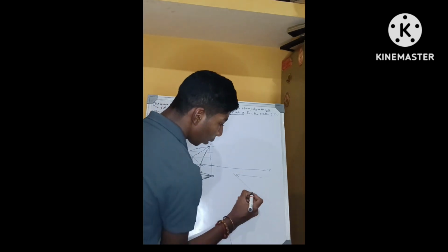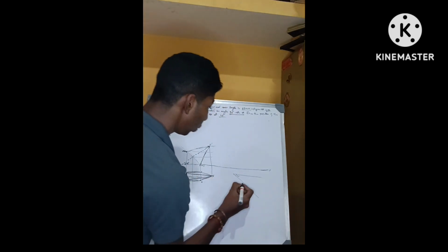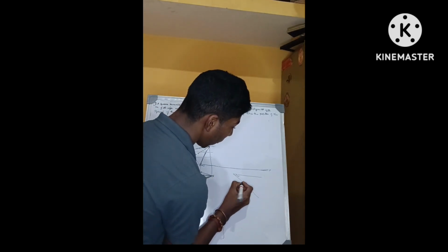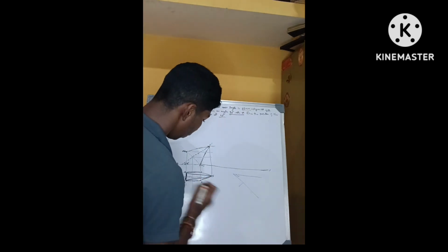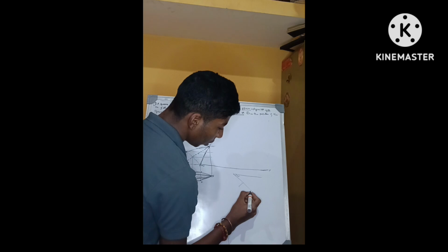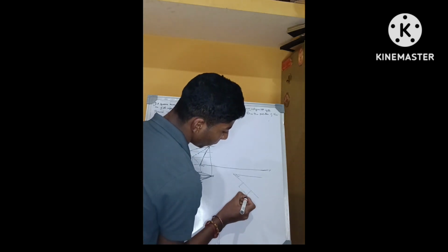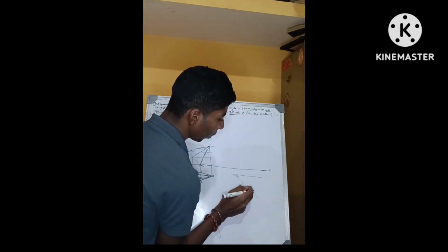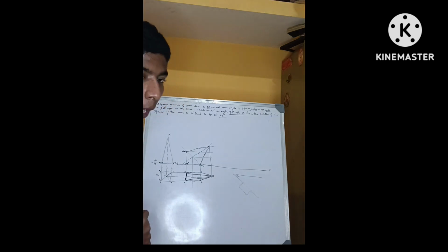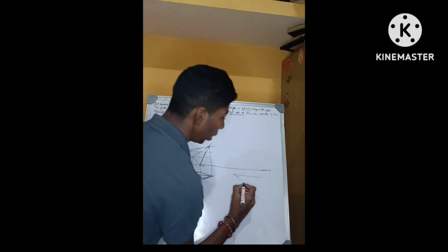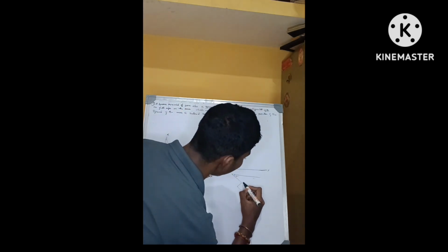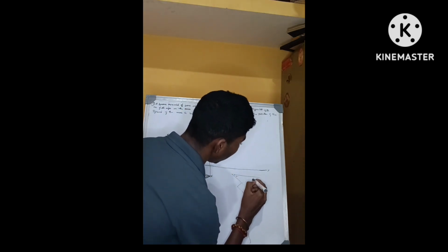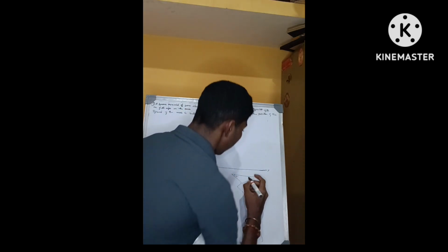You can convert it now itself or you can convert it later. Now again, just take C to D as the radius. Cut an arc. You'll get a point somewhere here. Join this. Next, B to A. You'll get here. Join this. Again same. You got it. Now convert it into an invisible line. Now take from C to O as the radius. Cut an arc. You'll get here. B to O, again same. You got it here. Convert it. Connect it, I mean join the points.